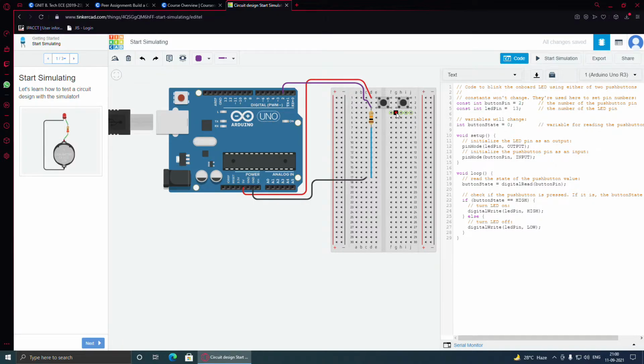So terminal 2 of component B and terminal 1 of component A will be interconnected. As I said, placing a wire or a terminal in any of the 5 holes of a row means they are getting connected together. These 5 holes are internally connected. This holds true for all the rows from row 1 to row 30 in this part and also in this part.